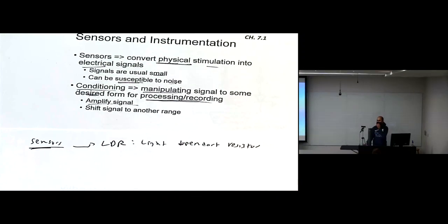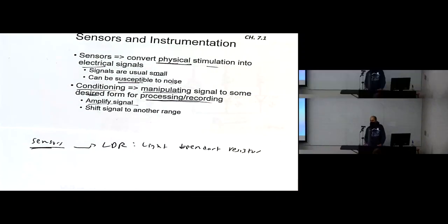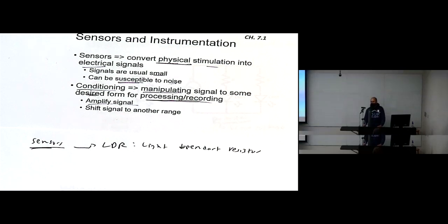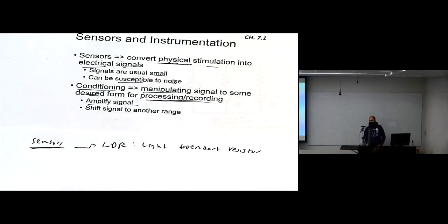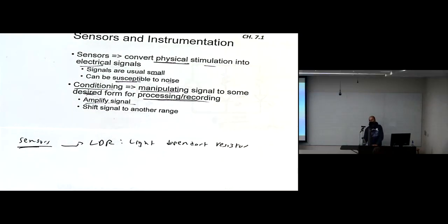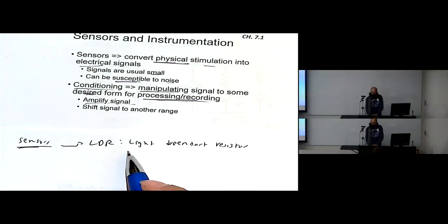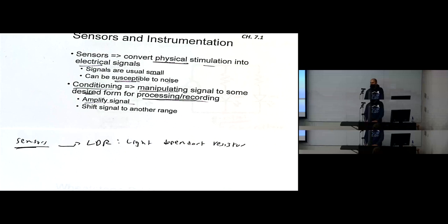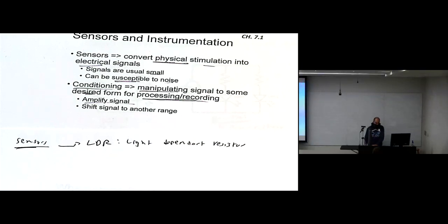And basically this is a resistor changing its value depending on the lights. So based on that, I can convert the lights to an electrical signal. So what's happening after that? I can do some action to them. So for example, if I have street lighting, if there's sunlight, turn off all of these street lights. If there is no sunlight, turn on. So we can use LDR in street lighting, which is light dependent resistor.